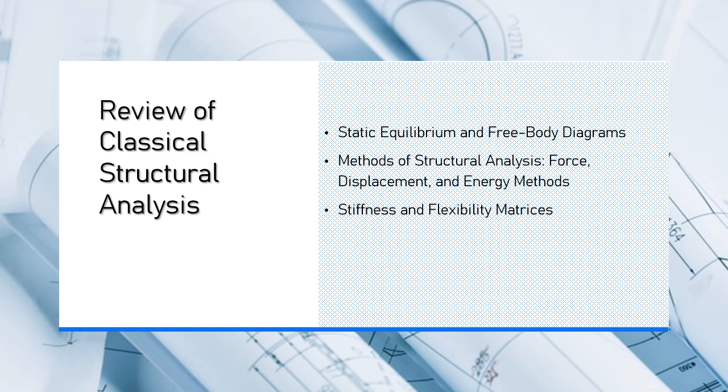Moment equilibrium. Use the moment equilibrium equation, ΣM = 0, to solve for unknown moments or reaction forces. By applying these equations systematically, we can determine the internal forces, shear, bending moments, axial forces, and displacements in the structure.